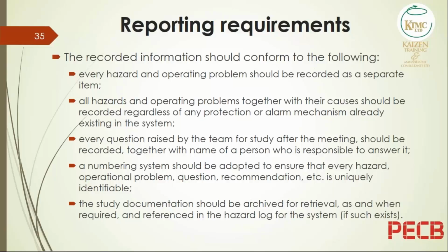Every question raised by the team during the study should be recorded. And of course, the name of the person responsible to answer it. A numbering system should be adopted to ensure that every hazard, operational problem, question, recommendation, etc. is uniquely identified. The study documentation should be archived for retrieval and, when required, referenced in the hazard log for the system.